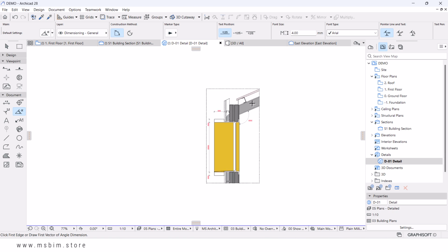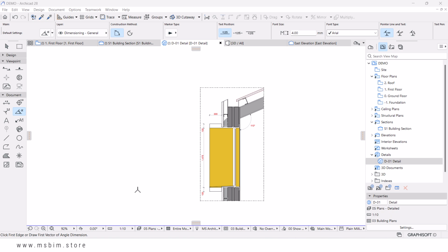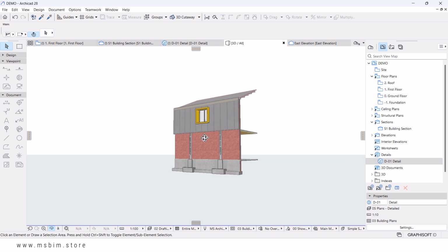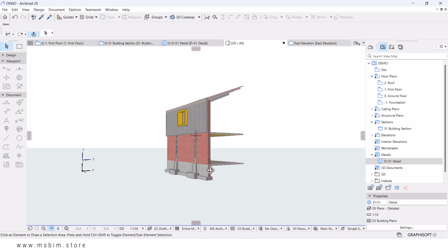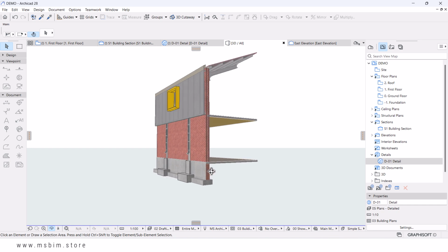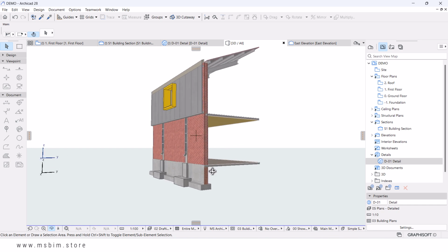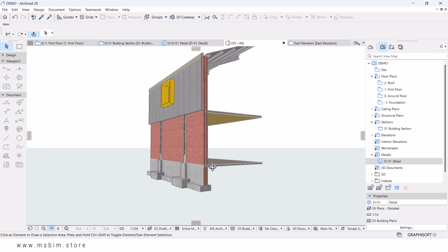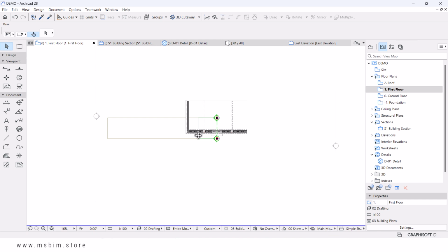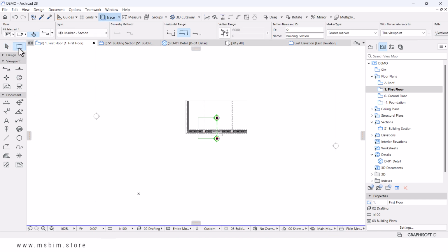Okay, let's move ahead. One most interesting part of this is to create 3D presentations, 3D section presentations view as well, just to a little bit show or flex your muscles and present well your project. So let's go to the 3D window, and I'll choose a view that I would want to add like that. Mainly I would want to have it as a section, so I'm gonna go here on the floor plan. Then let's get or activate the marquee tool.